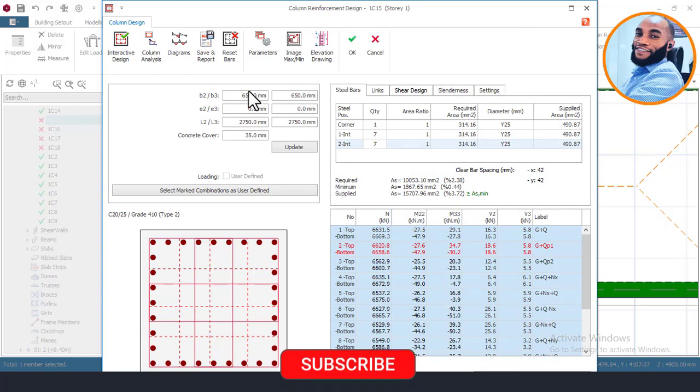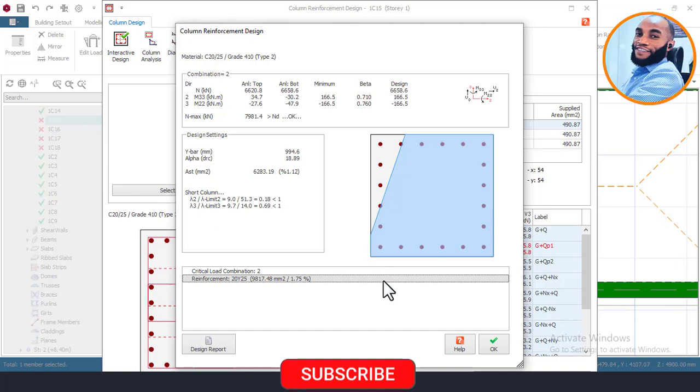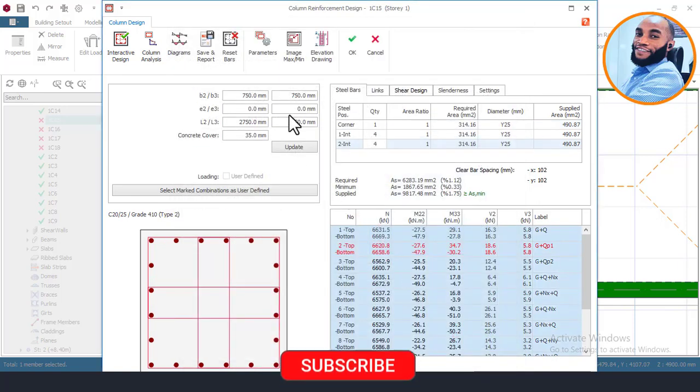And then I can choose again to make it, let me say 700, or 750, but just to maintain uniformity of my columns and to avoid too many groups of columns, I can choose to do that. So let me just choose 650 since that was okay and then okay. So I have explained more about the column.